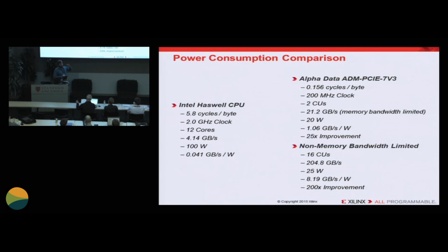And so every single time the clock ticks, there are 64 bytes of data being processed. So if an Intel architecture had a 64-byte wide SIMD component, then it could maybe do a little better. But that's something that probably doesn't make sense for the general use case. So this is just one way that FPGAs have a small advantage, because they can create these massively parallel pipelines. Okay, thanks.